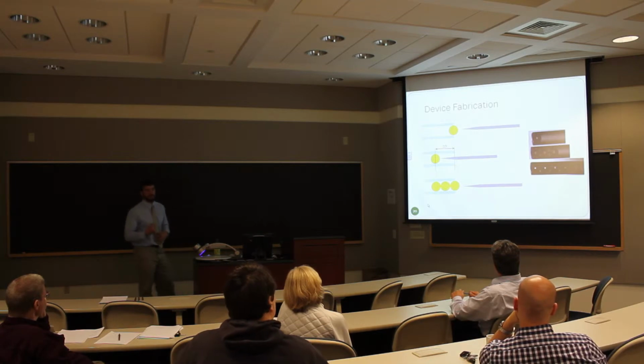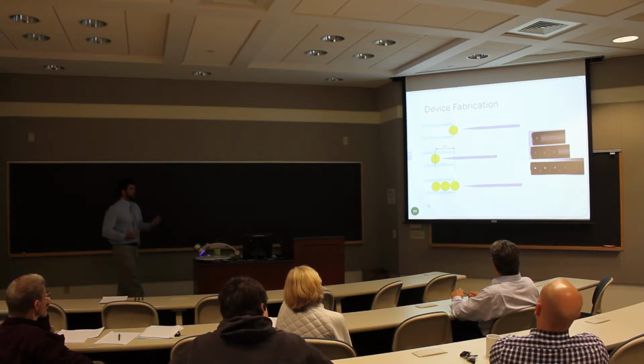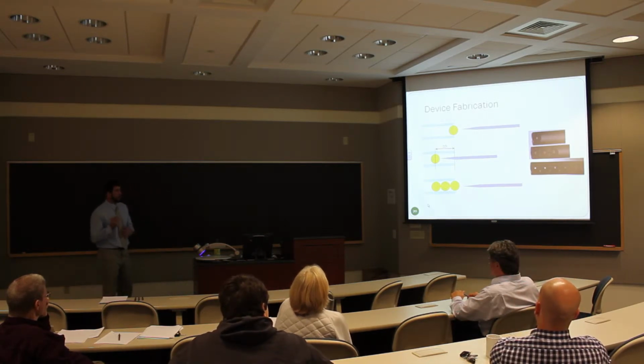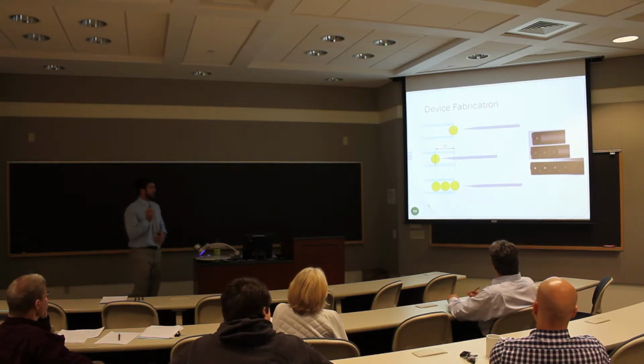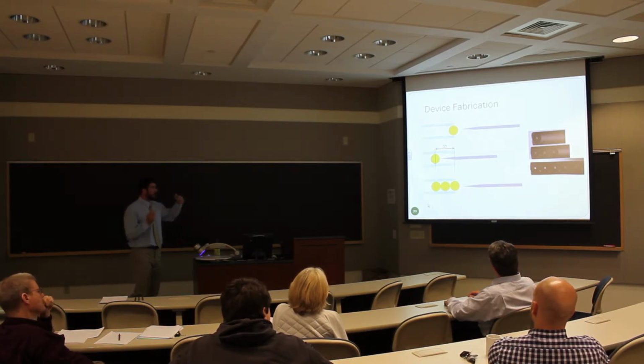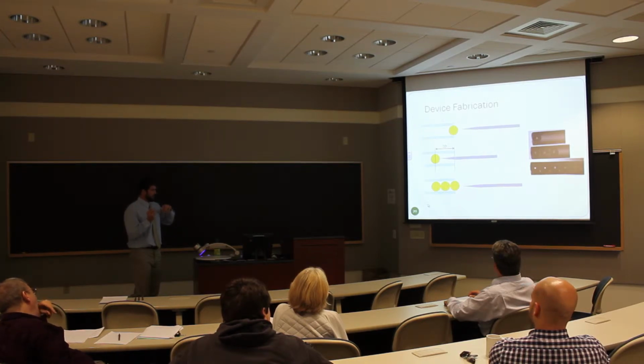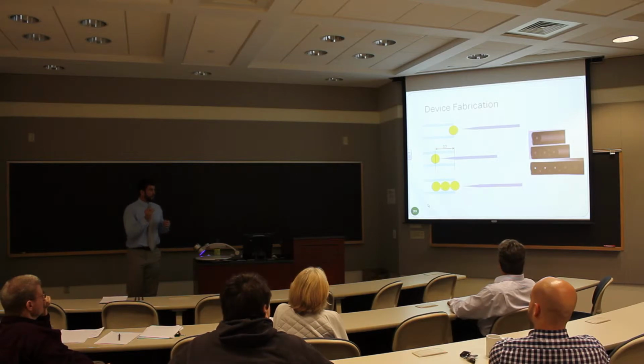Okay, we wanted to experimentally verify or test this modeling, so some sort of prototype or device had to be fabricated. So you micro-manipulate a sphere to the end of the tubing, use a micro-manipulation tool to push the sphere to your desired length, and then you just pack in the number of desired spheres, and that's shown here.